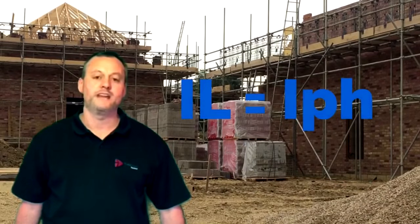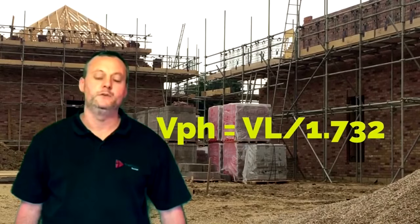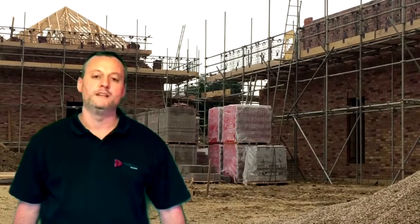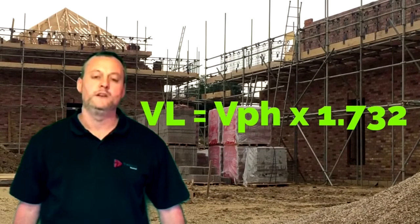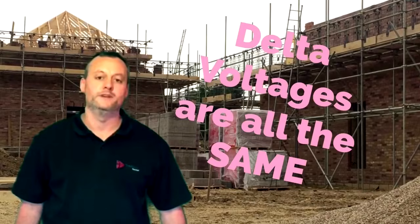But in a star connected load, what is common, the line current and phase current are both the same. If you knew the line voltage in a star connected load and you divided it by 1.732, you would get the phase voltage. If you knew the phase voltage of a star connected load and multiplied it by 1.732, you would get the line voltage. So let's recap. Easy things to remember. Delta connected load has no neutral, therefore the line and phase voltages are equal. The currents are out by 1.732.